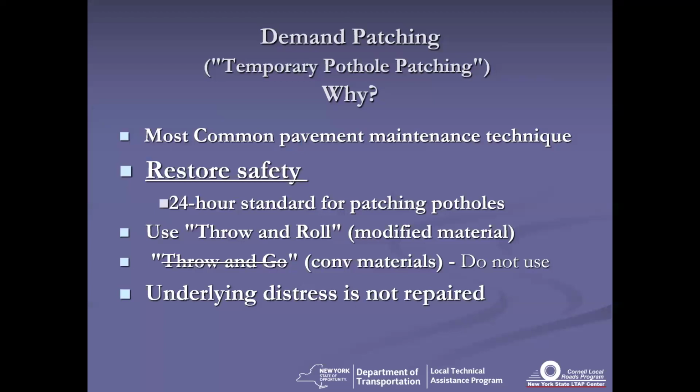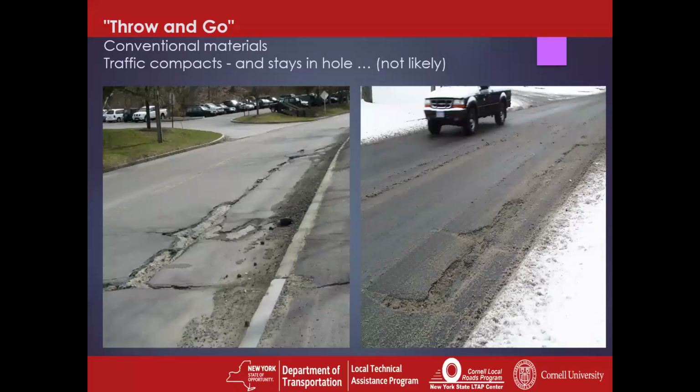Now, what we stress here is you want to be using the throw and roll technique, that is using a modified material. A lot of places used to use the throw and go approach, that was using your conventional pothole patching materials. We strongly recommend you don't use it because, as we'll show, it just doesn't last. In any case, your underlying distress is not repaired. You got to get in and do more extensive repairs once the weather gets better and the asphalt plant's open.